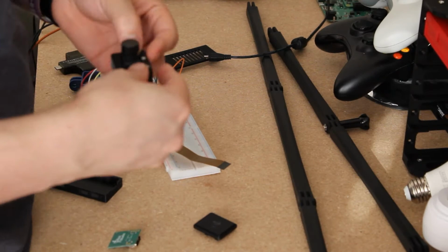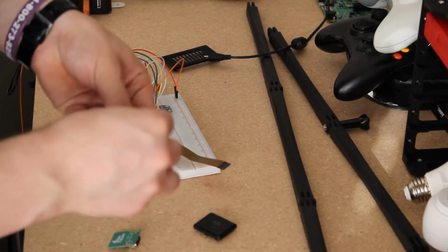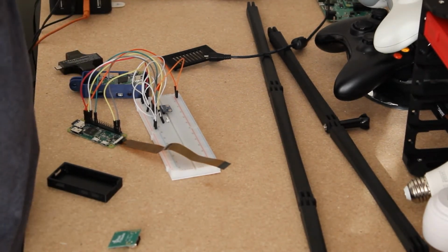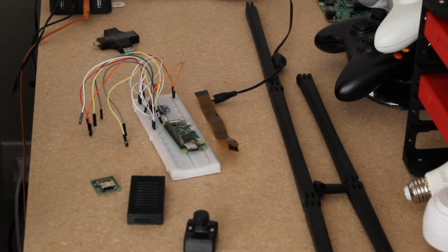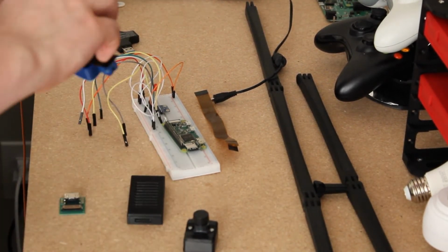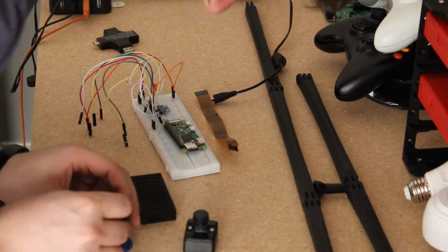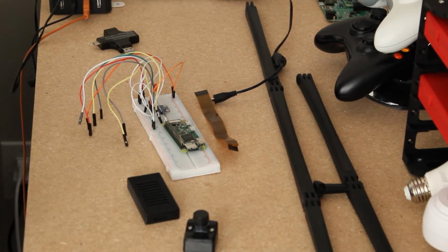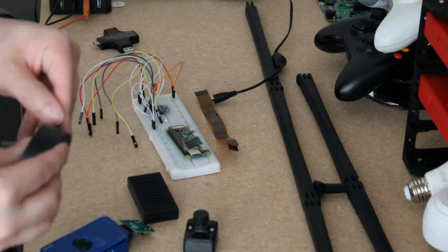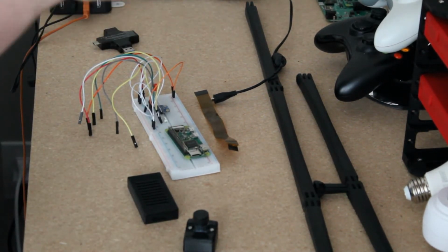I did make a change and printed out different extensions for the camera in order to make everything lighter, but also did not have the weird 90-degree connection ends. Another change I made that I wanted to do was to use the lighter and cheaper HDMI cable because it's much easier to manage as it's not as stiff. The only problem is that, like I mentioned in my previous video, these passive CSI to HDMI converters don't work on all the cheaper HDMI cables if they're missing a certain ground wire in them.